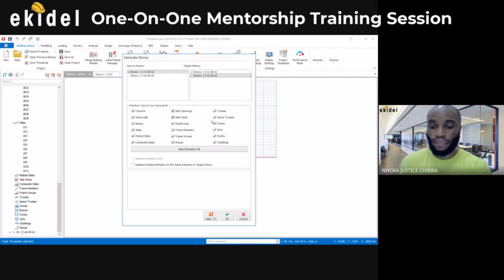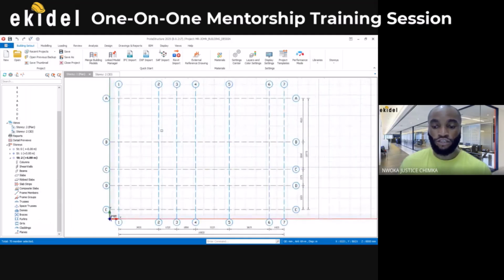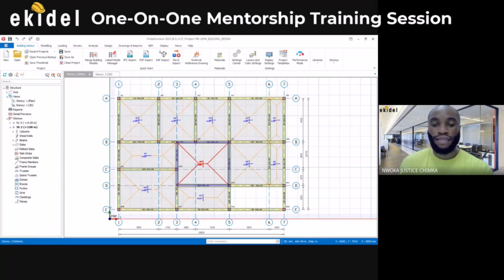So now, let me just pass through the main step. I'll come back here now and delete this one, which is story 2, which I just did before, that has nothing with it, only the grid line. I'll take it off by clicking and then say remove story. I'll say yes. So now we are left with only this story 1.